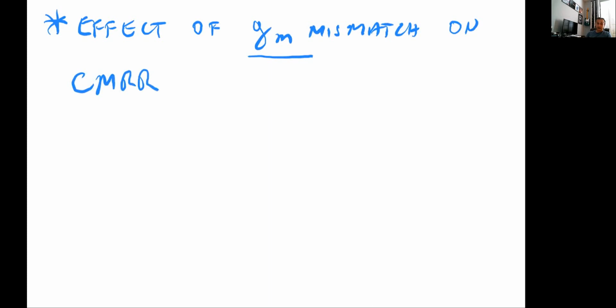So we can write the common mode gain, we can approximate it by, now we're looking at, if you wanted not to work with deltas and you wanted to make a continuous or infinitesimal analysis, this is equivalent to taking partial derivatives for each of the quantities that you are looking at, and looking at the sensitivity of the quantity, in this case, the common mode rejection ratio, due to that specific parameter.